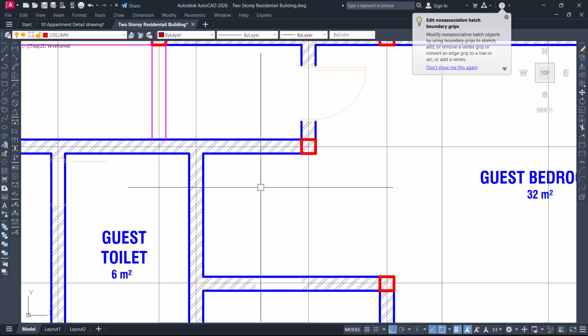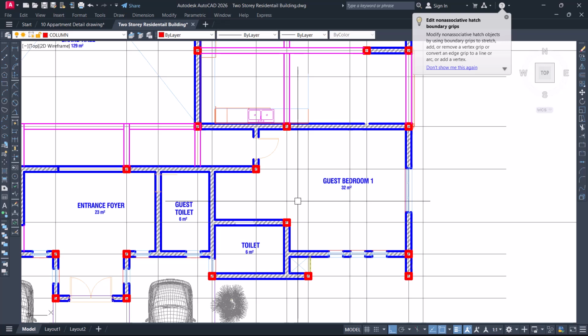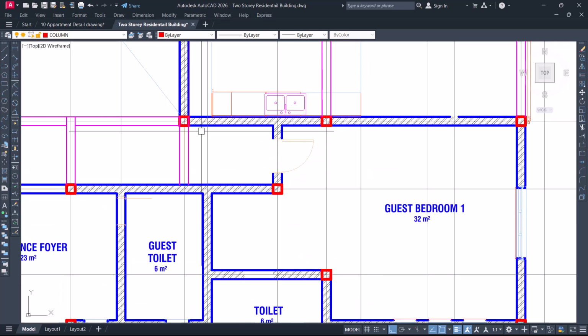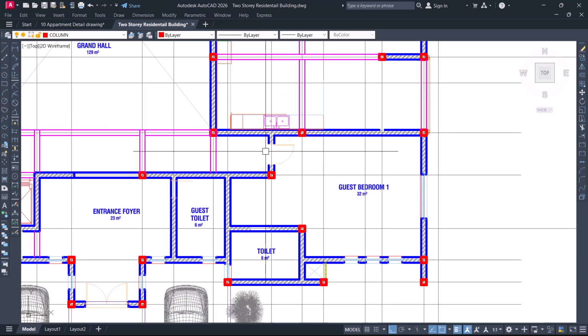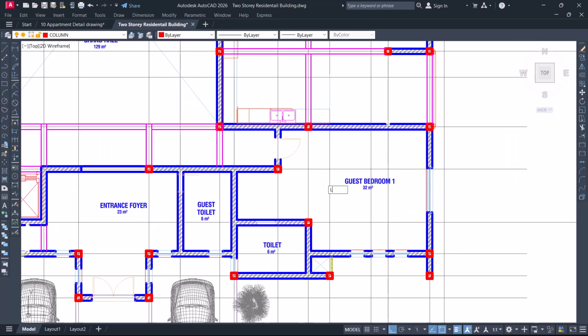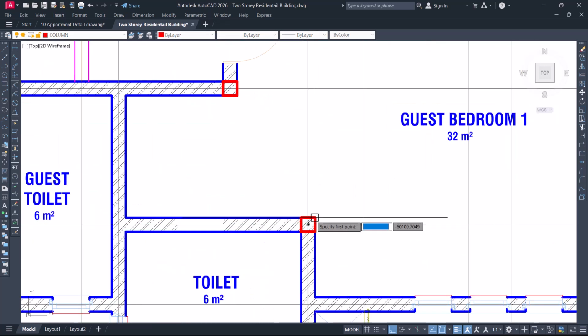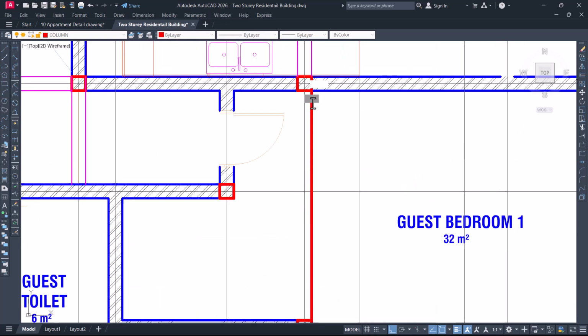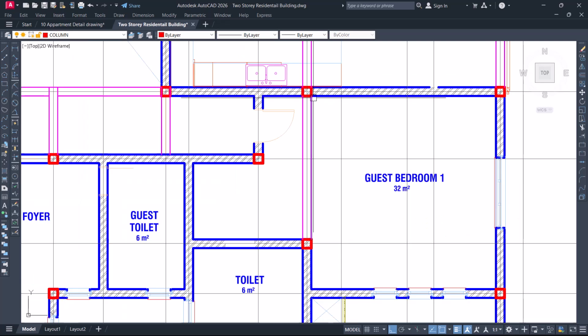So now I want to have, let me see, I also remove this too. This panel is too small to have it as a panel. So I want to combine something now. I will have to throw a beam from this point to this column here. Right? Then offset the beam thickness 225. Then make it a beam that does not carry block wall, because there's no block wall here. This is just used to separate this panel, to break it.